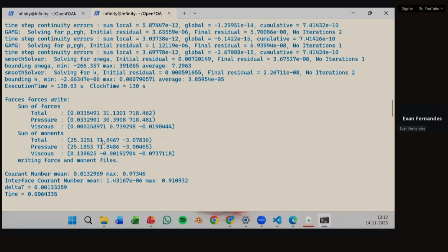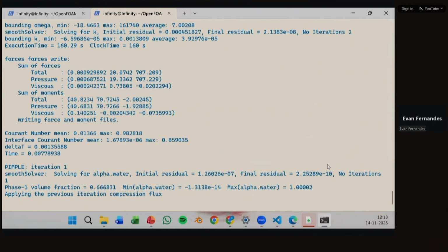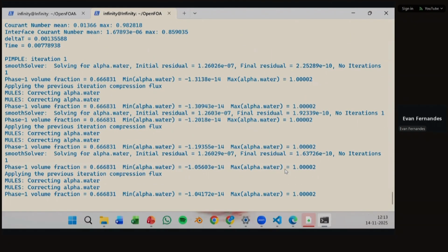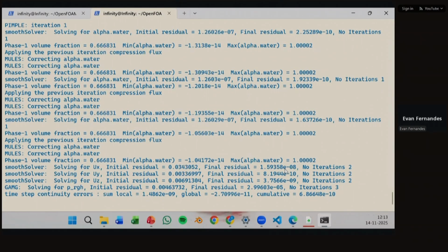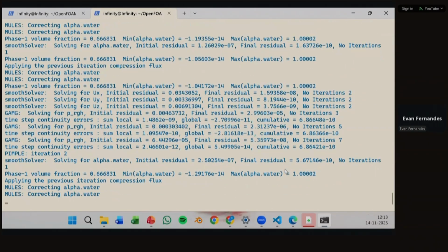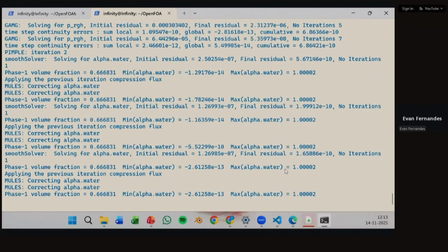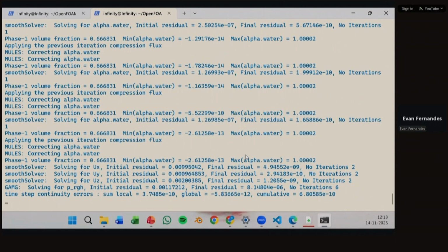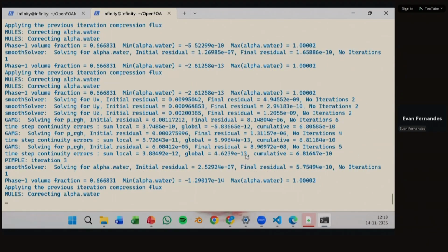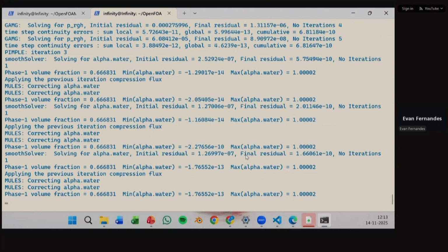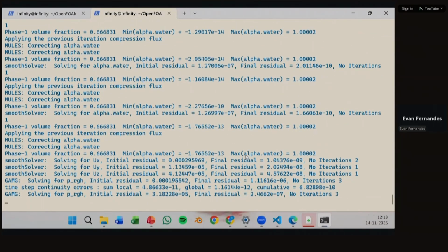This helps when you are not sure whether the parameters that you set are correct or not. At that moment, you can just switch off your simulation and start a new one. Because sometimes it may happen that you have done your whole simulation and then you realize that you forgot to place one particular parameter, and now you have to rerun the whole case, so that much time has been wasted. So for those kinds of cases, it's always good to check whether these parameters are accurate enough or not.